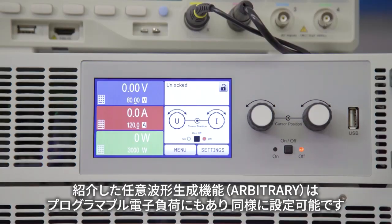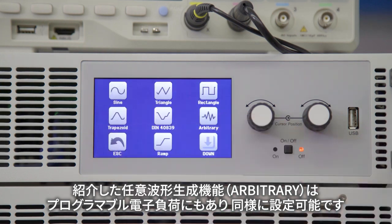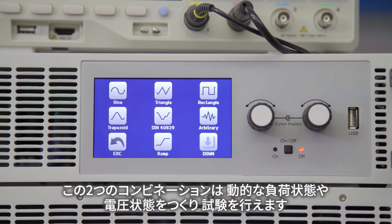That same arbitrary waveform and function generator that we saw on the programmable load is of course also available through the same menu structure on the programmable DC power supplies. So between these two combinations, you can both create dynamic load conditions and dynamic voltage conditions to really fully test your product.